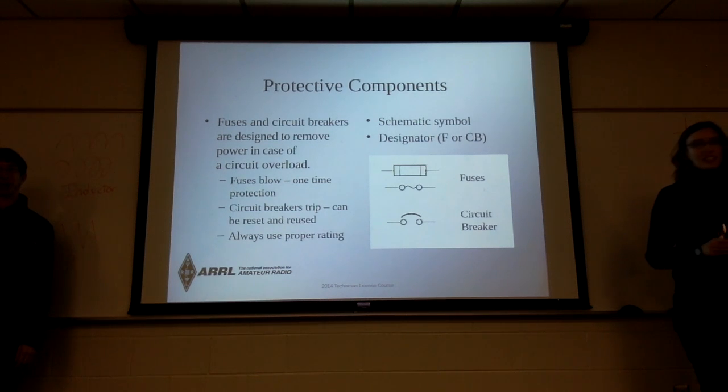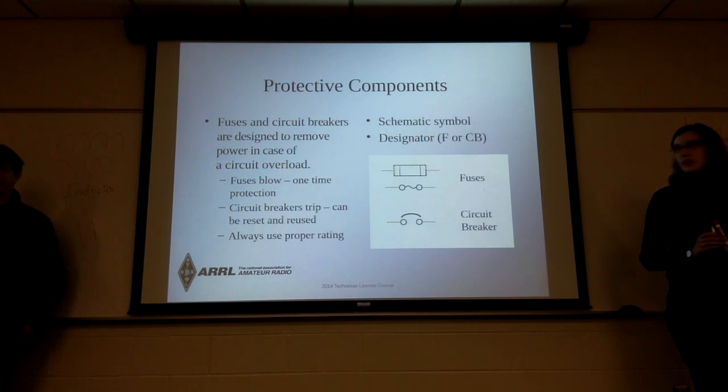Yes, and unfortunately, while the house is burning, the pennies will not, because they were designed for many hundreds of amps going through a penny before it will melt, whereas fuses maybe 20 amps. Well, the other feature is you could screw a light bulb into that same hole and use it to figure out when you found the short.